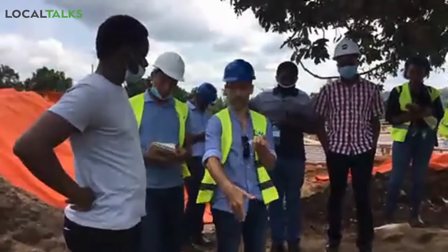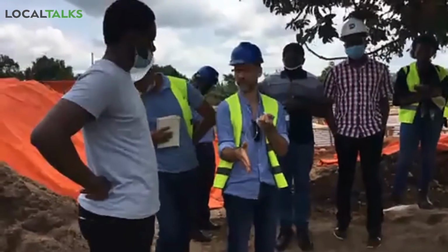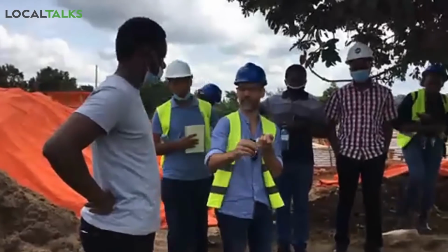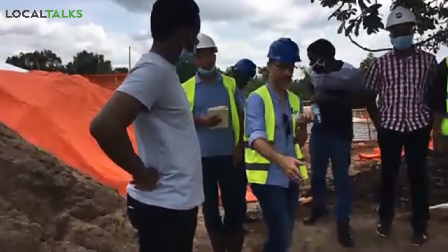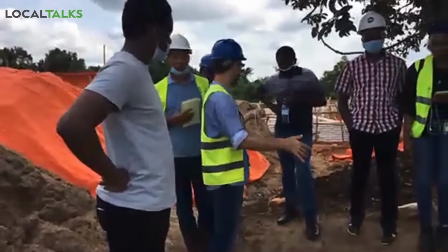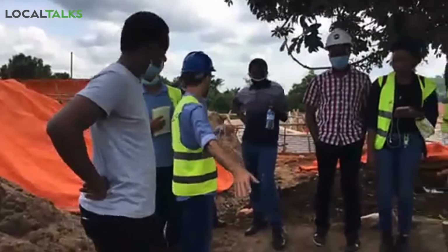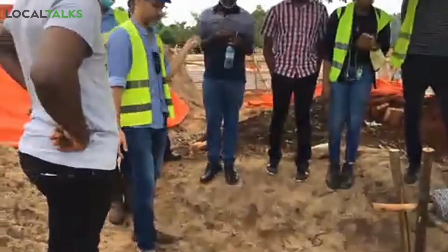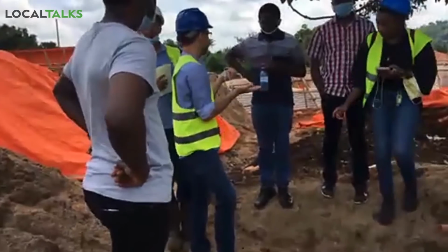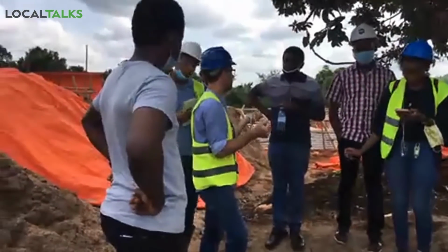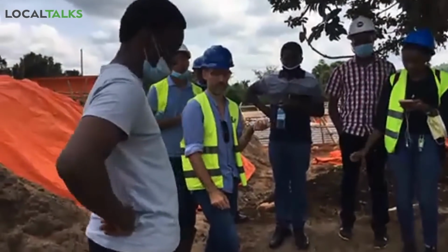Actually it was 1 meter deep. Then first came the slab, and the slab sits on top of the foundation. Yeah, the concrete slab. Then come the 3 layers of stone DPC, then we start with the earth. So I think that's also another aspect. This is of course a single layer of stone laid in a bit of earth. We did this not to mimic anything, but just to provide a flat surface to compact against. But what I'm trying to say is that in the buildings, the triple layer of stone DPC was a lot more stable because it was in a mortar bed, so it wasn't wobbling as much as what we've seen now.